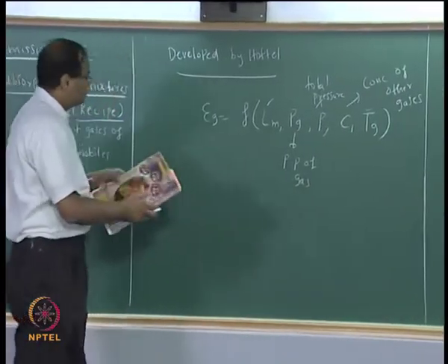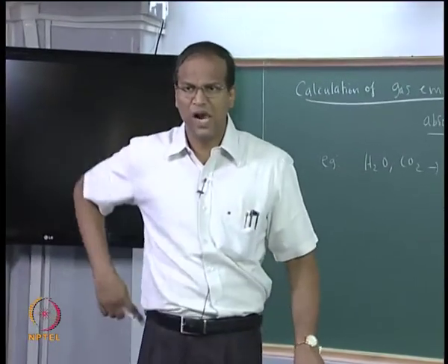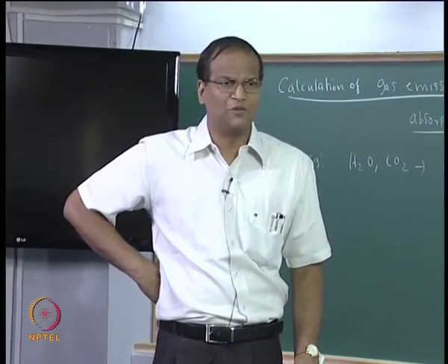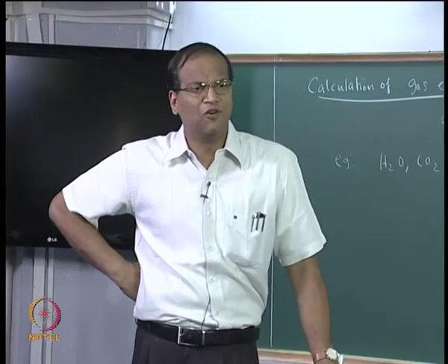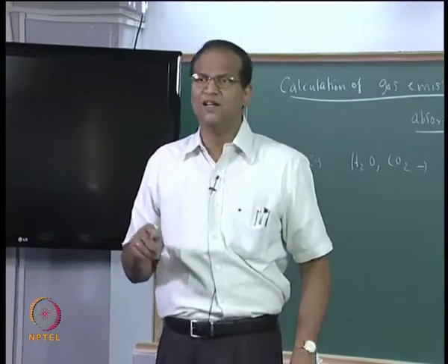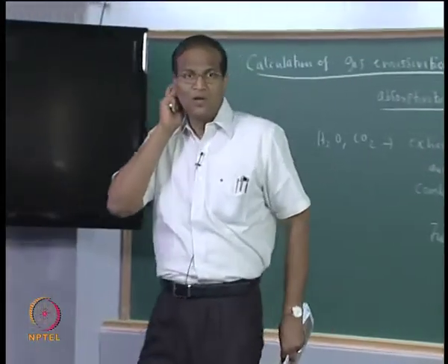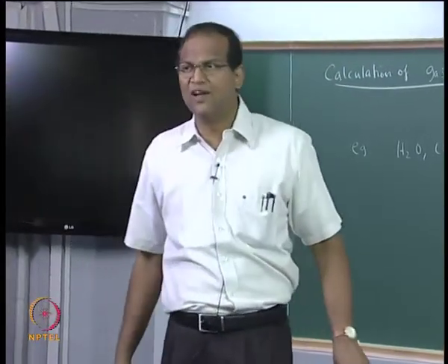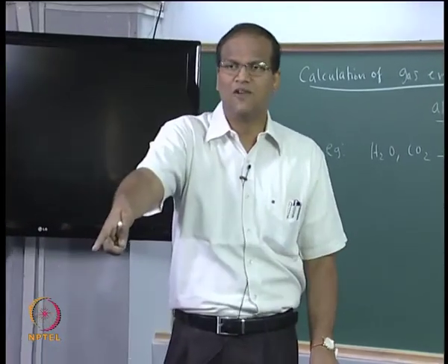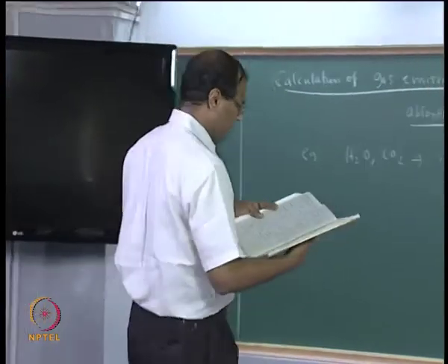Now the total pressure affects the emissivity because, among other things, the total pressure also gives you an idea of how much gas is contained in some particular volume, and then because of that the intermolecular spacing will change, and because of which its capacity to absorb and emit will also change, correct. So first of all, the baseline charts have been developed for a total gas pressure of 1 atmosphere, and then some correction charts are also available which will correct for pressures other than 1 atmosphere. Okay, so once we do a problem it will be clear.